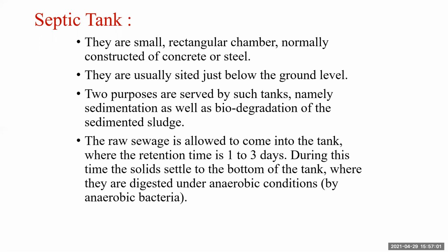During this time, the solids settle to the bottom of the tank, where they are digested under anaerobic condition by anaerobic bacteria. Okay, so what happens? First, the raw sewage is dumped into the septic tank, where it is retained for a period of, say, 3 days. During this time, solids settle at the bottom, where they are digested under anaerobic condition by anaerobic bacteria. That means clarification and thickening is achieved.